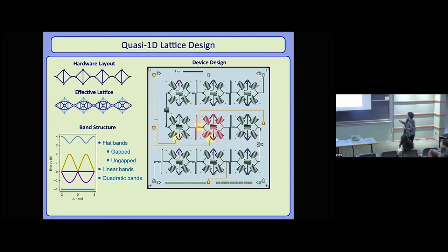In addition to the qubits, you might notice the little purple caterpillars that are crawling everywhere over this device. The transmon itself is a relatively large perturbation on the resonator. You have to carve out a chunk of the ground plane and then put in these extra capacitor paddles.